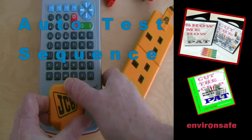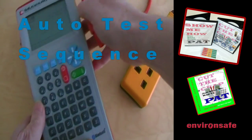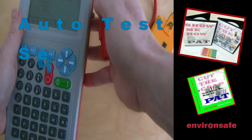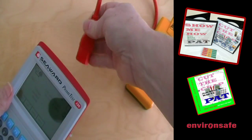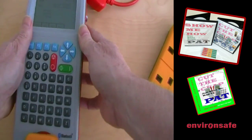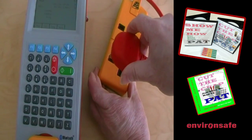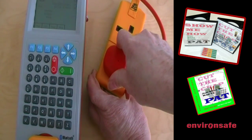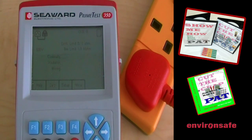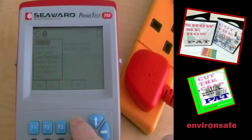Connect the extension lead to the tester. Connect the IEC cord. Connect that to the other end of the extension lead. How to use the auto test sequence mode. F4 for menu. It's already set on auto, so F4 to OK that.